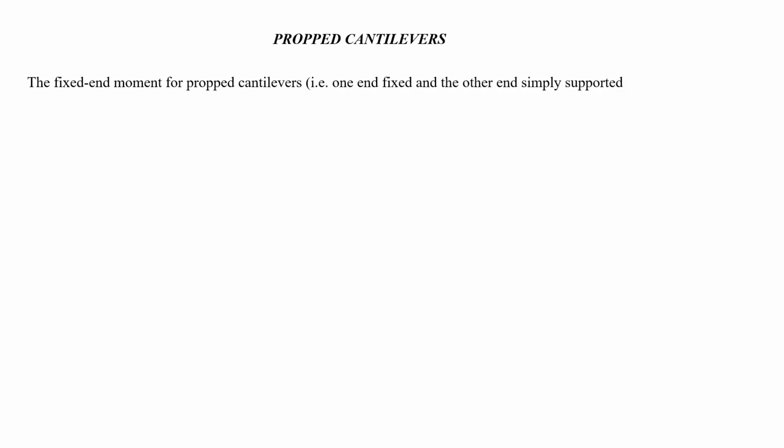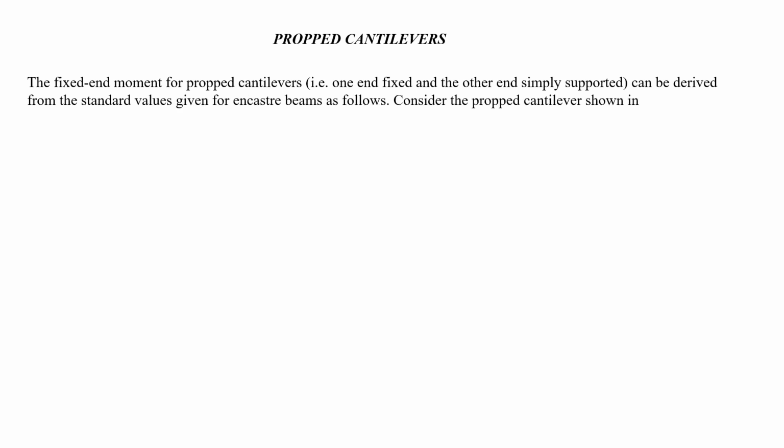Propped cantilevers. We will see one example. The fixed end moment for propped cantilevers, that's one end fixed and the other end simply supported, can be derived from the standard values given for the fixed beam and cantilever beams as follows.